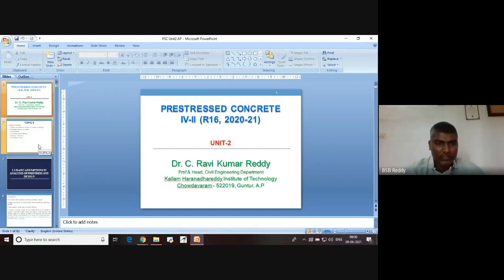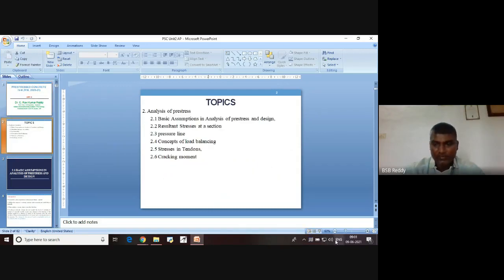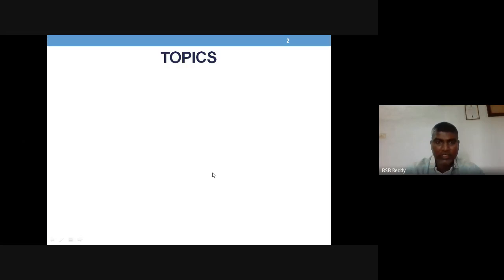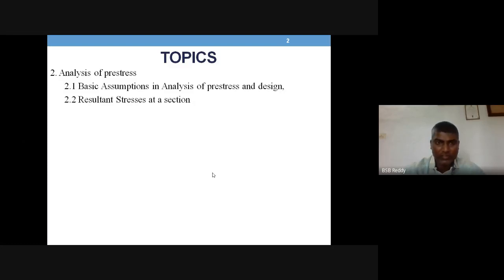Good, till the last session, we have talked about the analysis of pre-stress. Just to present you once again what we have in this unit 2. So we are talking about analysis of pre-stress. We have calculated resultant stress at a section by simple superposition of the stresses from pre-stress, like direct stress from pre-stress and bending stress from pre-stress, also bending stress from dead load and bending stress from live load. Those are the things done, and we have also